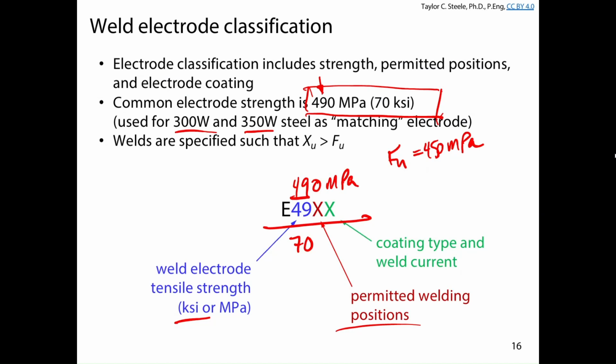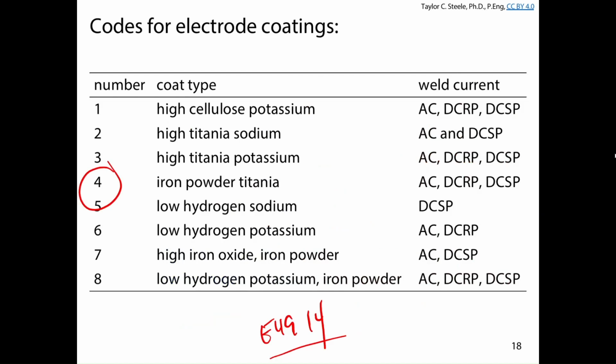Unless, from time to time, you're working on a brownfield site, that means stuff already exists. And there's an existing beam up there from 1950. And you know from some kind of test that it's a specific kind of steel that was made in Germany that has a really high carbon content. If you're specifying welds to that as an engineer, you need to specify a very specific kind of welding electrode here so that the weld metal is going to be compatible with that high carbon steel. If you just said E49XX, welder to figure it out, you'd be in trouble because that weld would fracture in almost no time. On sites with existing conditions, you have to be very careful about specifying welds.